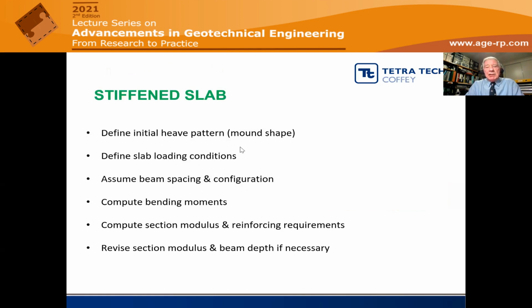And you need in the design to define the heave and the loading. You assume beam spacing and configuration. You need to work out the bending moments, and you need to have a structural analysis so that you make sure that it is both structurally and geotechnically adequate.